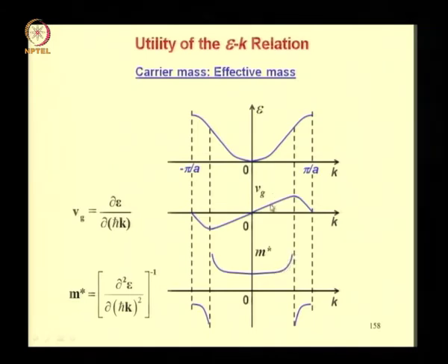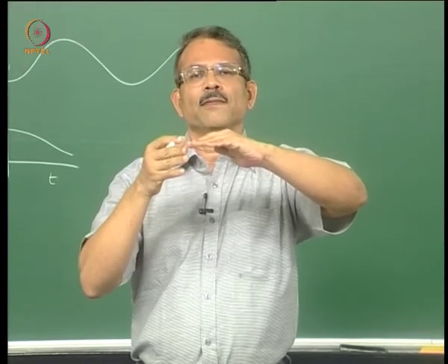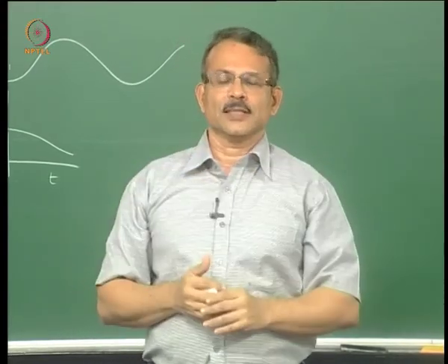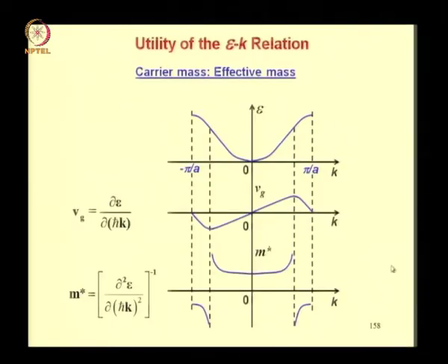So the velocity increasing at a decreasing rate here in this region is because the effective mass is going on increasing. So your force is constant, the mass is going on increasing, so the amount of increase in velocity is going on decreasing. So that is how it is, and very interestingly the effective mass is negative for electrons near the top of the band.